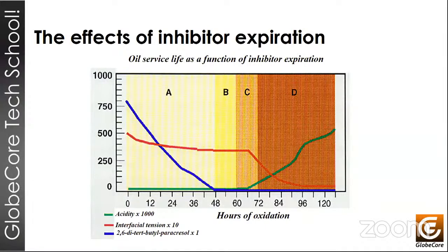So we can see that when the oxidation inhibitor expires, the changes don't really take place immediately. There is a delay, but we can already see some change in the color of the oil, and this gives us the false impression that there is no problem with the transformer, which is not true, because what happens is that the transformer itself works as a filter, I guess, of sorts that absorbs the pollutants, and gradually the oil becomes darker.